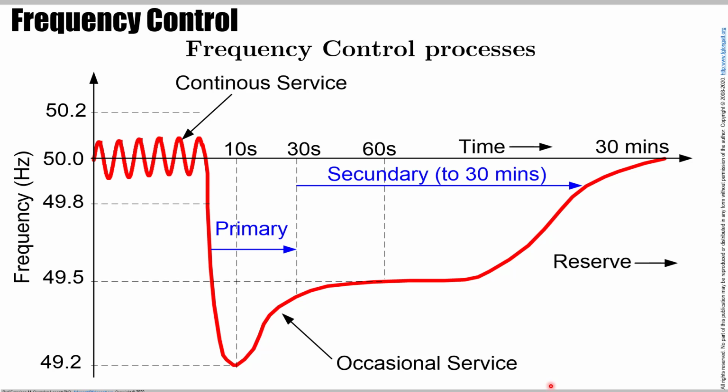The situation starts to get complicated when we have a system frequency disturbance. For instance, we have the sudden disconnection of a big generator. We have a generation deficit. I mean, there is more load than active power provided by the generators, and as a consequence, the frequency drops. That is what is happening here.